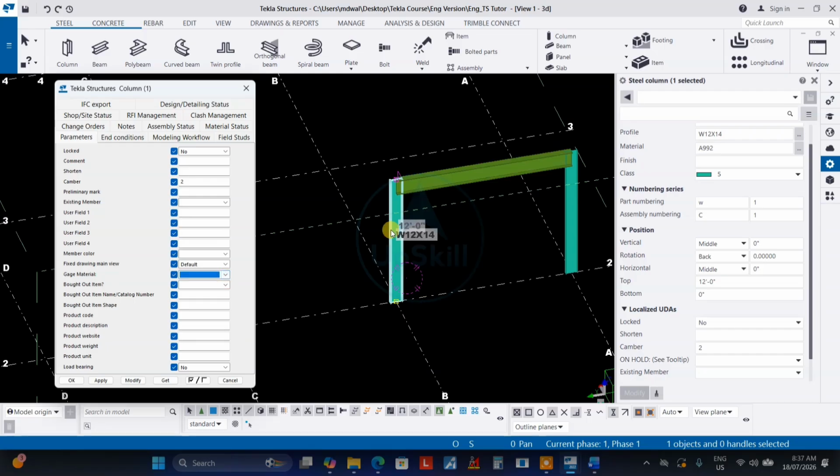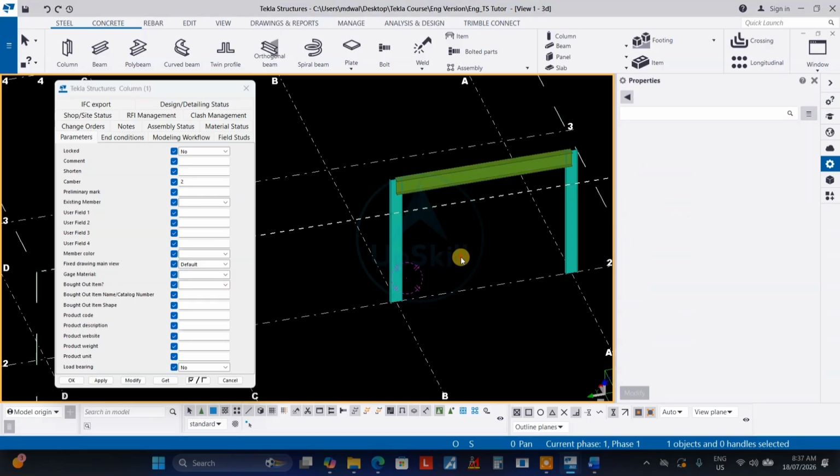Gauge material. In the hot rolled section and US projects, sometimes we are giving 8 mm material, and sometimes the fabricator or erector wants that one in GA. So if it is 8 mm material or 1/8 inch material, 1/16, 3/32 like that, we need to convert here.